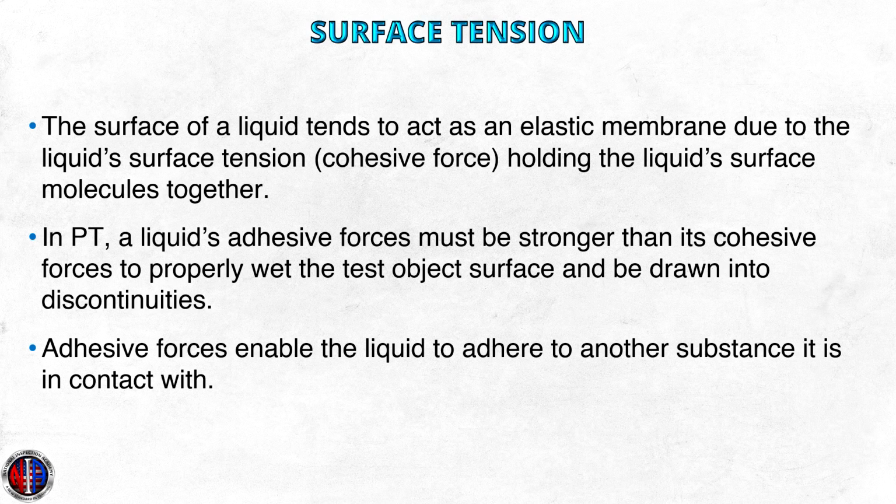The cohesive forces creating the surface tension can be very strong. However, for PT liquids, the liquid's adhesive forces must be stronger than its cohesive forces to properly wet the surface and be drawn into discontinuities. Adhesive forces enable the liquid to adhere to another substance it is in contact with. These cohesive and adhesive forces are important in what is known as wetting ability.